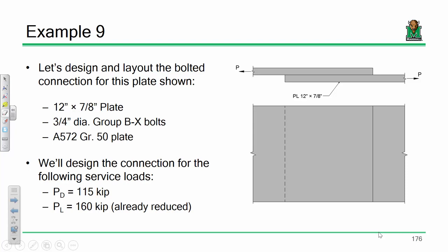So you can usually handle that in a design scenario. Just make sure that you're using the same dimensions and the same grades of steel, and you're good. And if you use the same dimensions, but the steel grades are different, just check the one that's weaker, and you know you're going to be fine. So, like I said, you usually have a good bit of control over that in design.